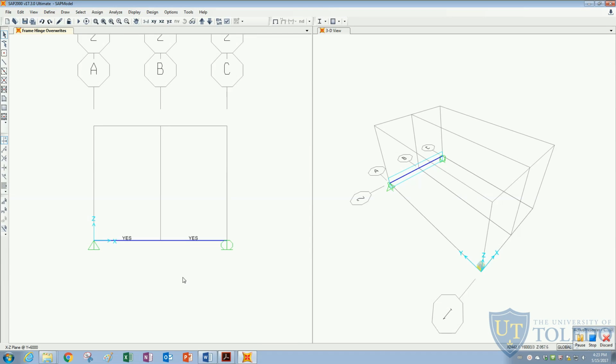So now that we have everything set up here, let's talk about the load that we will input on this beam. We don't know where this beam will fail, so we don't know which load we should apply here. Before we do anything in SAP, we should have an idea of how much load this beam can take. For that, one easy, fast way to have a sense of how much this beam will be able to sustain is to do hand calculations, using the coding provisions, for example. I already did that, and I figured out that by the ACI code, this beam should resist about 430 kilonewtons, and at failure it should displace about 25 millimeters.